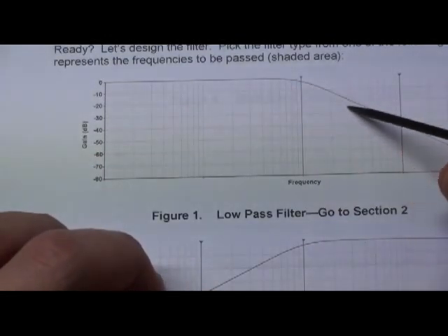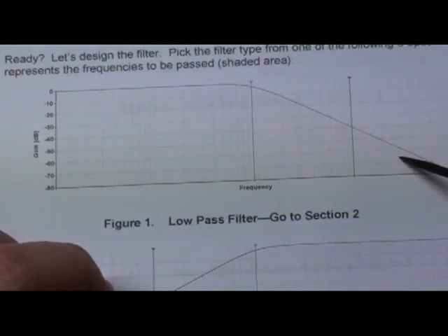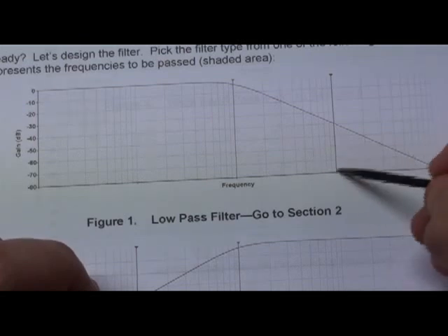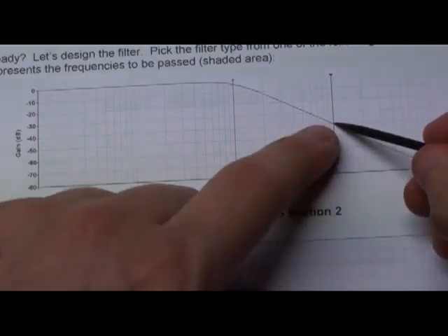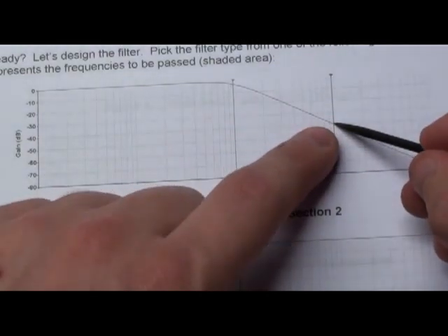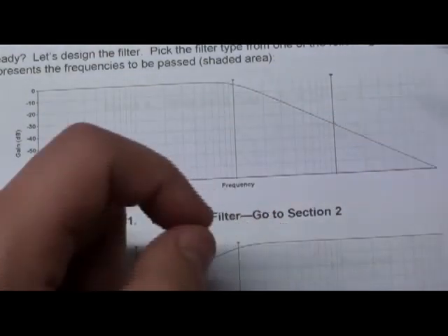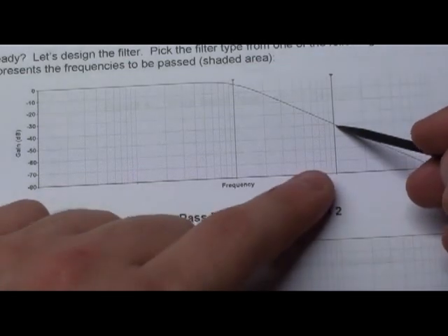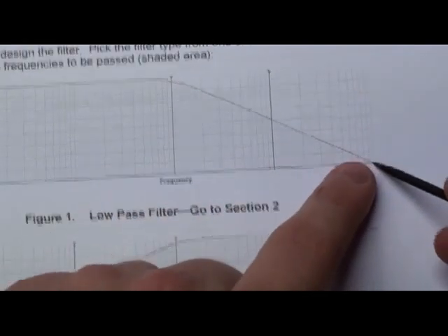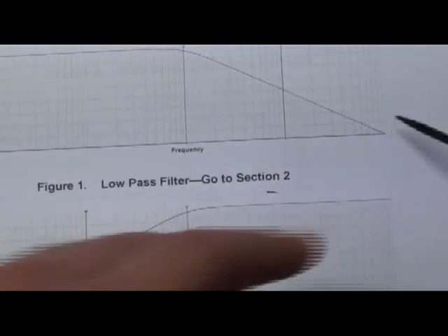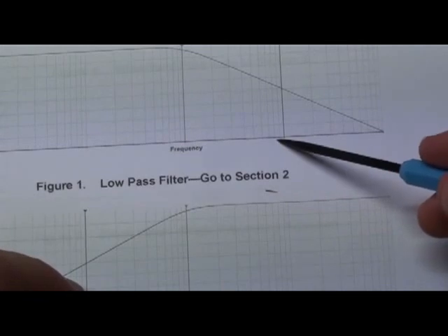And then as we go down, down, down, let's say this here was 100 Hertz. So now any 100 Hertz signals we put through are going to get pretty small. This is going to multiply them by half. And then as we get further and further, it's going to multiply them by very, very small values, so they'll effectively go away. Now, this is what we want, right?